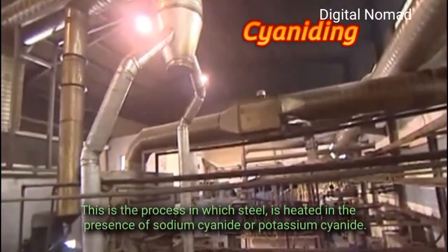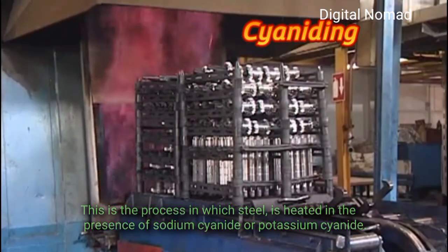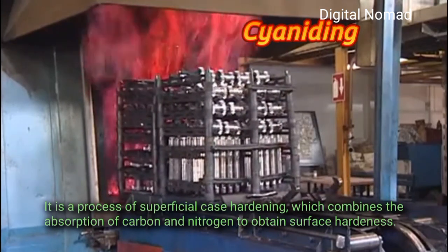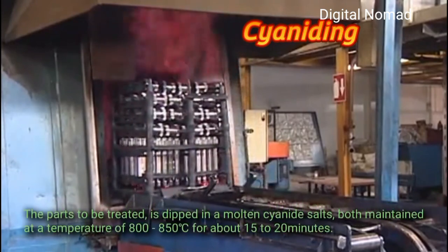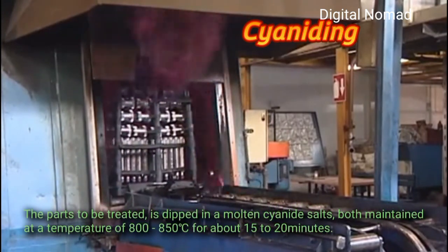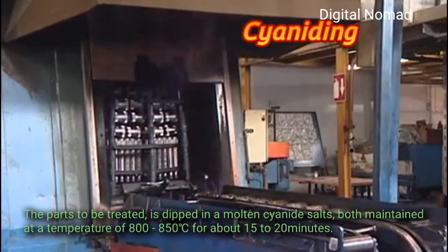Cyaniding. This is the process in which steel is heated in the presence of sodium cyanide or potassium cyanide. It is a process of superficial case hardening, which combines the absorption of carbon and nitrogen to obtain surface hardness. The parts to be treated are dipped in molten cyanide salts, maintained at a temperature of 800 to 850 degrees Celsius for about 15 to 20 minutes.